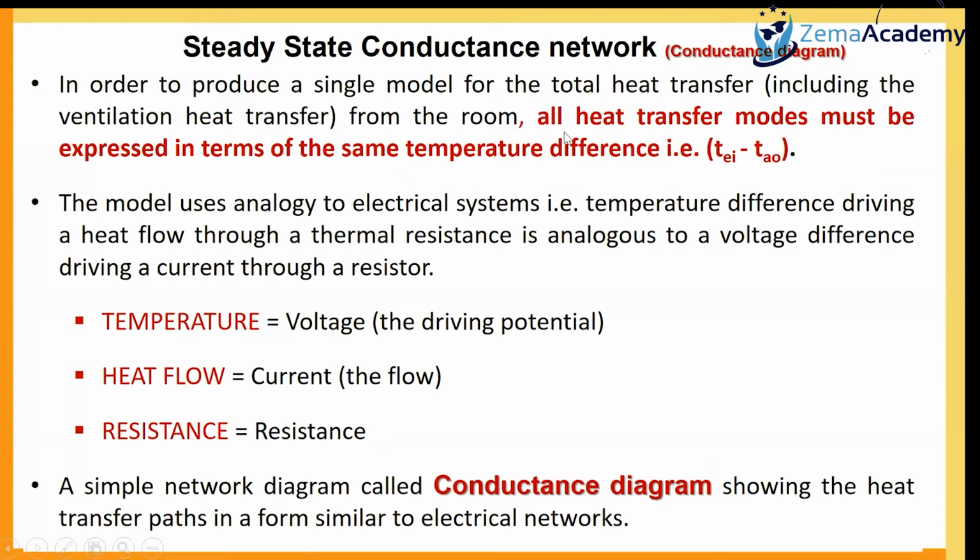And that's why you can see I have highlighted that all heat transfer modes that will be modeled from the room will be expressed in terms of the same temperature difference, that is between internal environmental temperature and outside air temperature. The model itself, because it's based on electrical networks, is called a conductance diagram. So what I'll do is take one step at a time, and in the end we will sum up all the branches together.